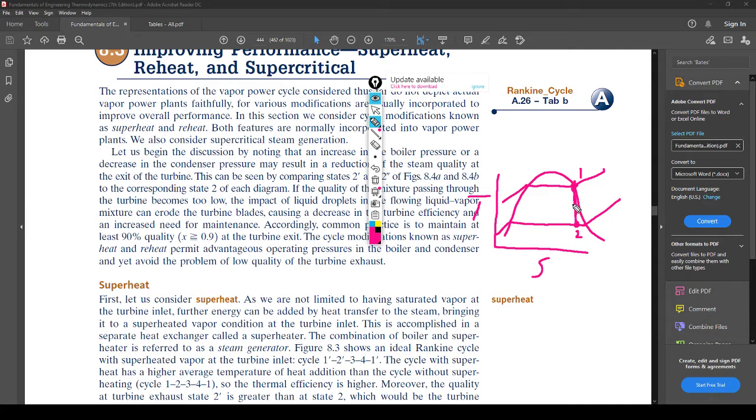And if you have too much of it, what ends up happening is that you will erode turbine blades, right? Think about it. It's hot water, metal, turbine blades, although I don't know if all turbine blades are metal, but there's probably some different ones. But essentially, what happens is you'll erode them, and when you erode them, the performance will drop. You'll get less power. You'll have to buy new ones. You'll have to maintain them. It increases the cost of the power plant.